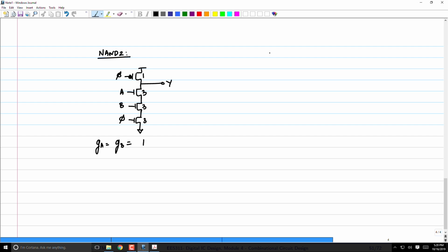Now what about NOR 2 logic? Again, one footer device, header device connected to the clock output. Now I need to have parallel logic here. A, B. This is my normal NOR gate. If I wanted a dynamic NOR gate without a footer device, it would be this.